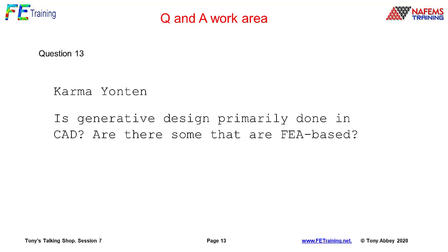No. In fact, generative design is done primarily in FEA. Design Space is using elements. We're knocking elements out. Our challenge then is to transition that Lego brick type definition of the structure with elements missing all over the place into smooth geometry. And the two programs I used here have two different approaches to doing that. So that downstream link back to something we can manufacture, back to real smooth stresses and so on, is very, very important. Generative design done in CAD is very interesting.